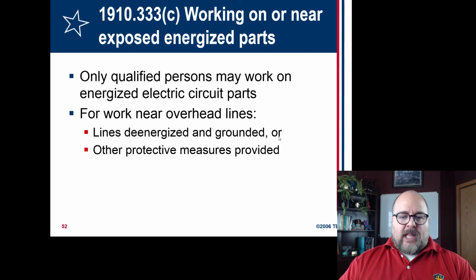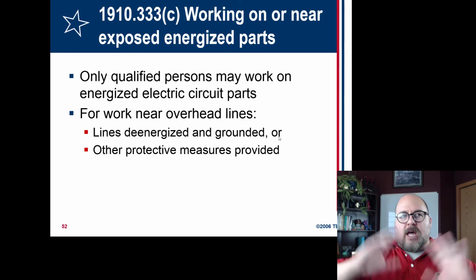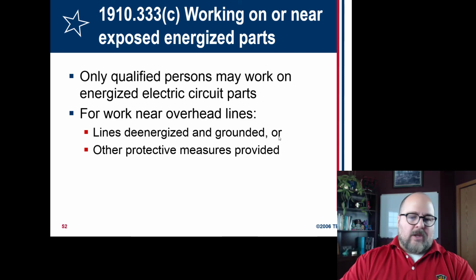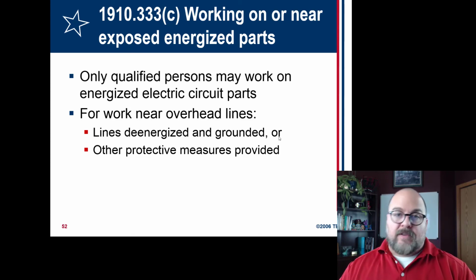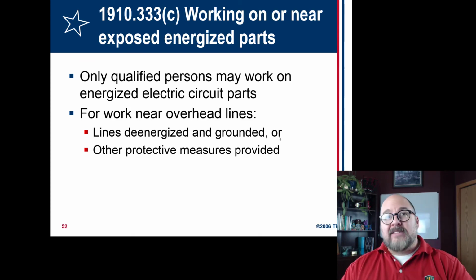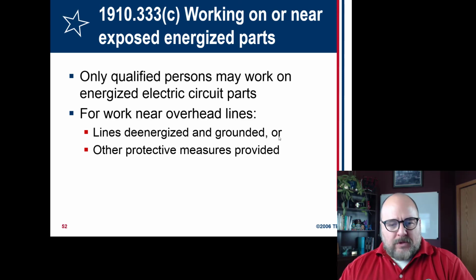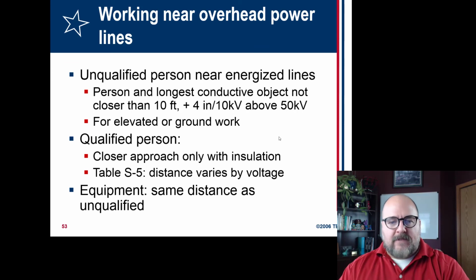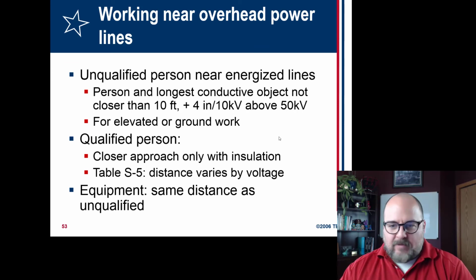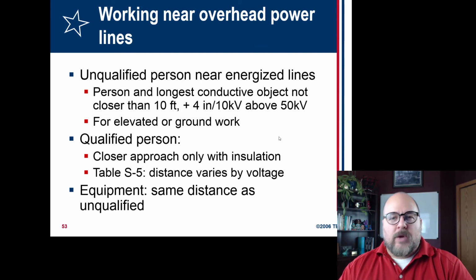Yes. For overhead lines, that's a whole other issue. It's high voltage. You should never come within 10 feet of an overhead line. And as it goes above 600 volts, I think it's another few inches every 50 or 100 volts or something like that. Oh, there we go. 10 feet plus 4 inches for every 10 kilovolts. You should never go near it.